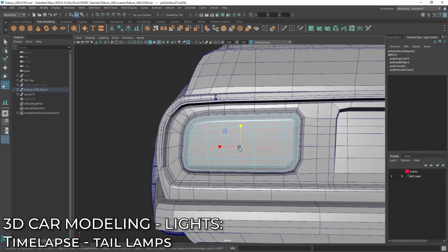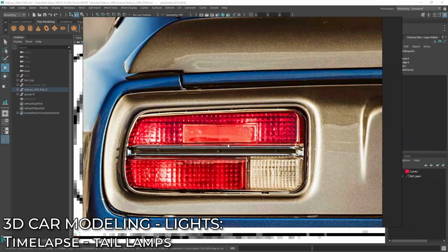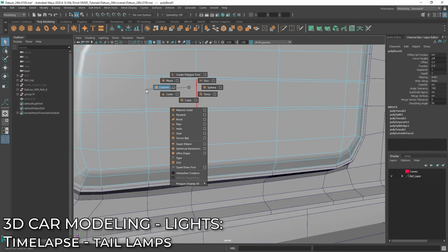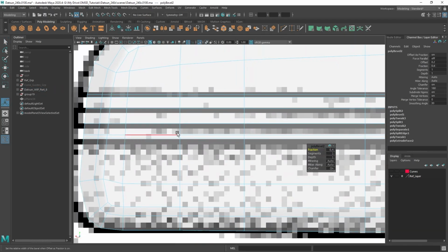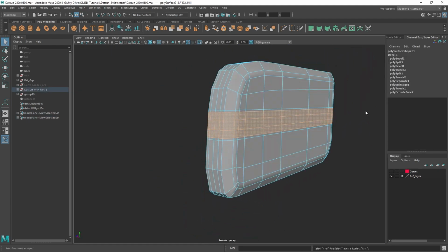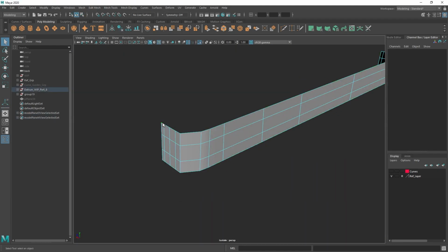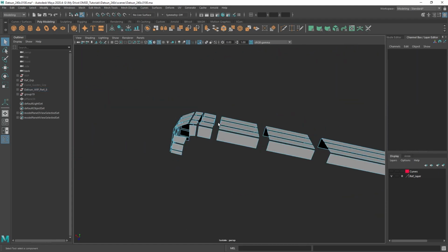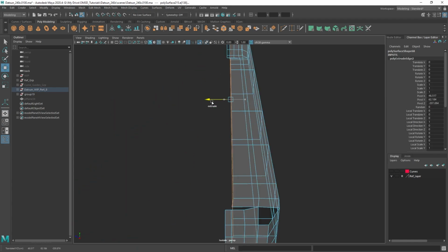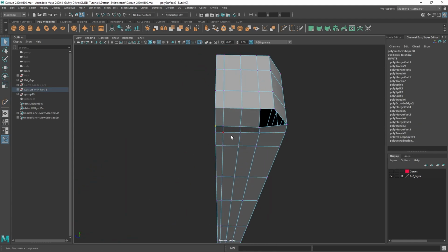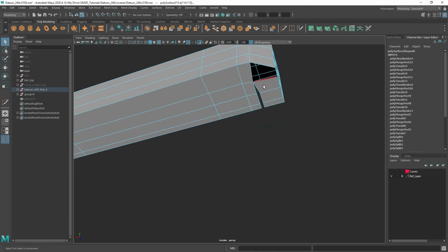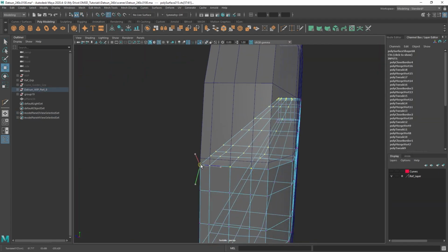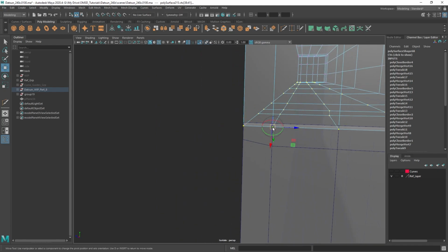All right, so here we are. You can see I'm going through and adding in that bezel. So I'm breaking up the solid piece of taillight geometry now. And I'm using that double bevel workflow that I use throughout the modeling series. And this is going to give me nice, clean, straight lines. And once I do that, I extrude back, clean up the extrusions a bit, connect the geometry, and make it look like a solid, nice 3D solid piece of geometry. Previously, it was just one-sided, so that's why I have to go through this step of extruding back.